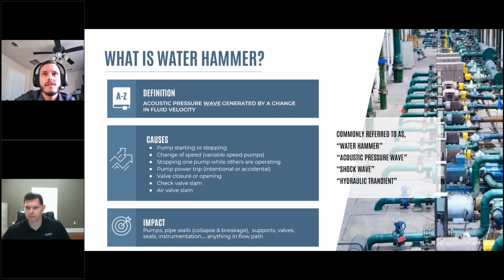Just as a review, if you attended our previous webinar, or if you're just jumping in brand new, what is water hammer? Water hammer is an acoustic pressure wave generated by a change in fluid velocity. That means it can be caused by anything that changes velocity.